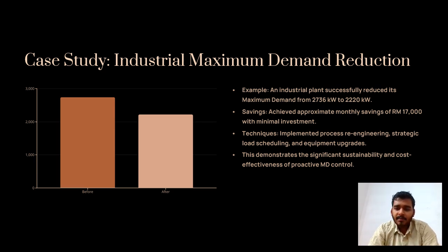Techniques implemented: engineering strategies and load scheduling, along with equipment upgrades. These demonstrate the significant sustainability and cost effectiveness of proactive MD control. MD means maximum demand control. Monthly and yearly costs can be reduced by the techniques of equipment upgrades and load scheduling. Load scheduling means peak load scheduling and demand load scheduling according to mornings and evenings.